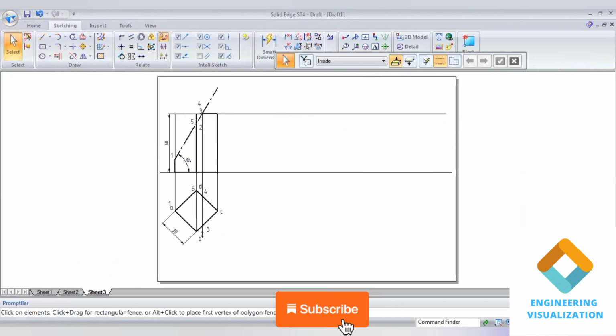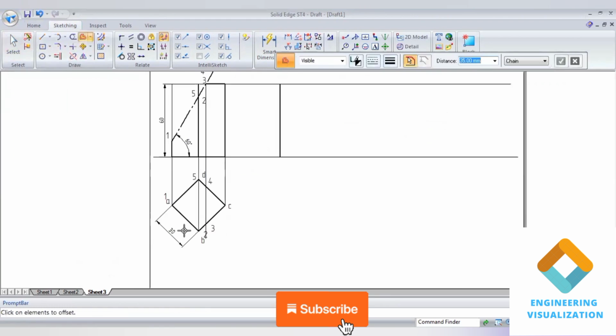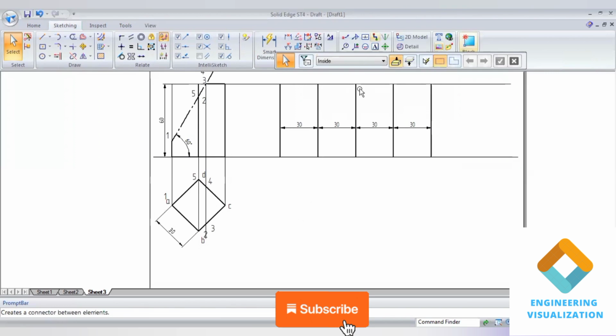So draw the projection lines from here, and draw the continuous line here. Now we take a vertical edge, because this is the parallel line method, since it is a prism. Draw a vertical line; anywhere you can take a straight vertical line. Here you can see the dimension is 30. There are 4 faces in the square prism, so using the offset command I will give a distance of 30 and click 4 times. I will get the 4 faces here. I'll make all these lines continuous.